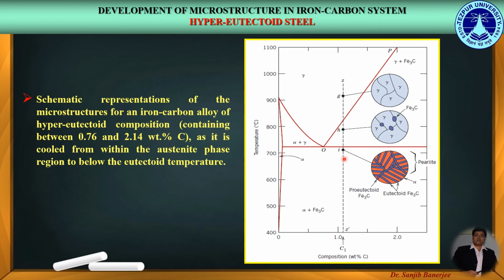So once again, in this iron carbon phase diagram, this dashed line represents the hypereutectoid steel, in this case of composition C1. Over here, we can see the uniform phase of austenite or gamma. Here, a combination of austenite plus cementite, and over here, a combination of ferrite or alpha plus cementite, together termed as pearlite.